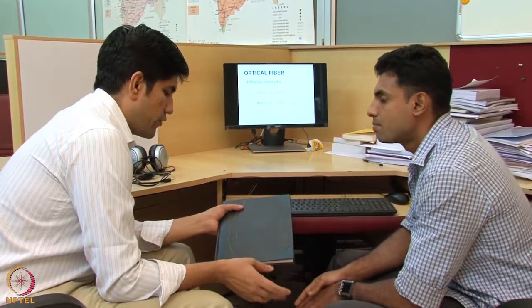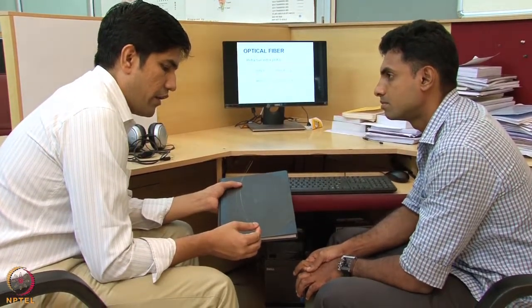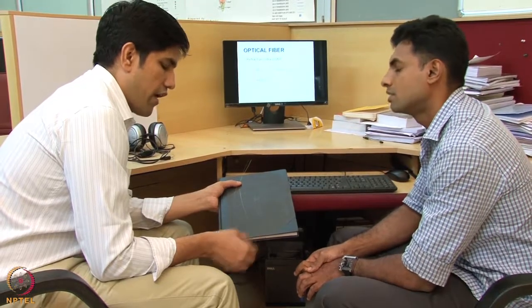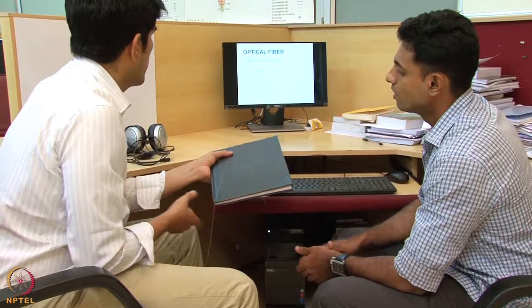So basically, when we talk about dispersion, we are talking about the group velocity versus the phase velocity. The dispersion error will be low at 1300 nanometers, whereas the wave decay itself, the attenuation, will be lower at 1550 nanometers. Okay, so let's look at the basics.